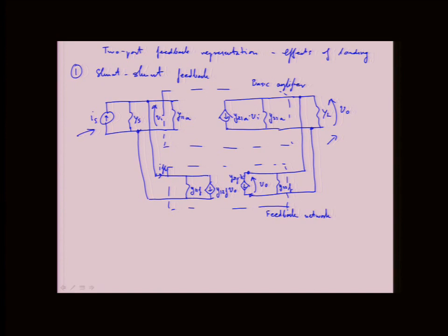And then, to be really general, the amplifier itself could also have a bilateral direction, or the reverse direction of signal flow, although we can in many cases just neglect that. But just for completeness, we can also add that. So this would be Y12A times V out.